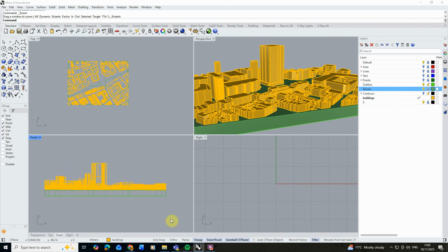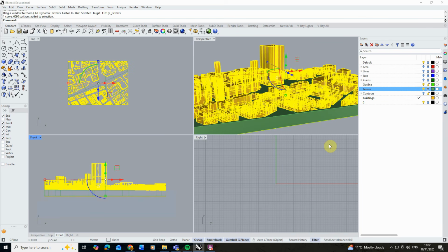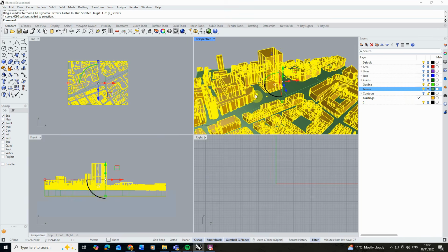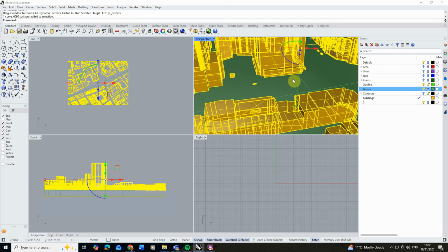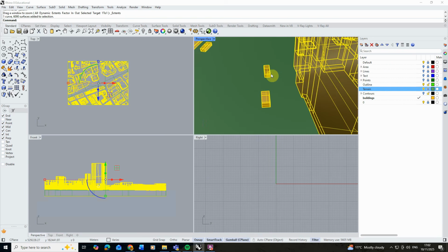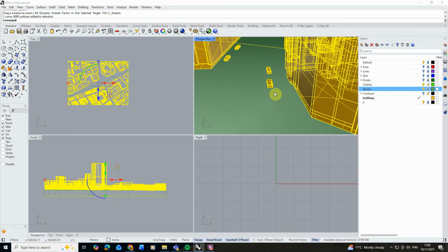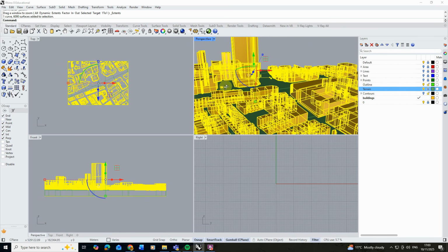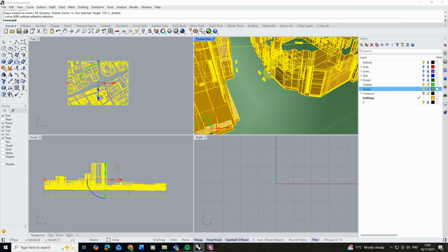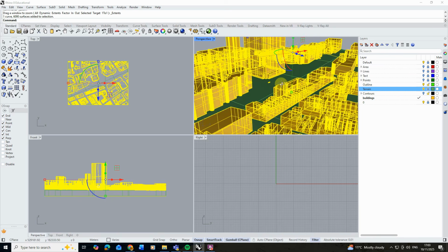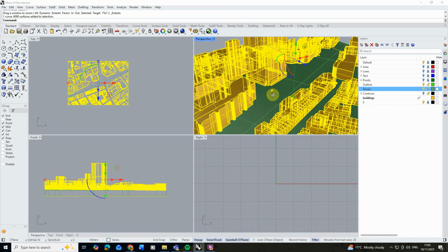With that front view selected, we're then going to use the marquee tool to select the very bottom of the model. So you can see here I'm just skimming that bottom layer. What this will do is select all the geometry except all the top faces of my buildings. This will also select some of these smaller ones, which I usually don't need because they're usually marking out smaller bits of street furniture, which for this I don't want too much. If you want to keep them, you can always go around and deselect them, but in this case I'm just going to delete them from this model.